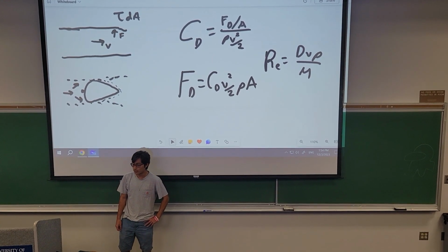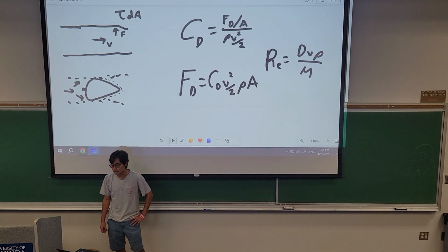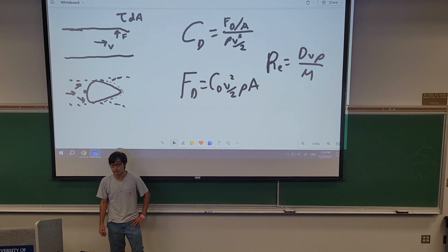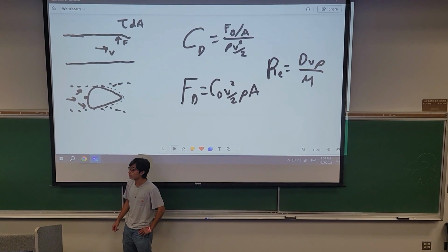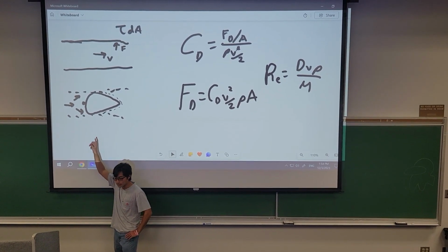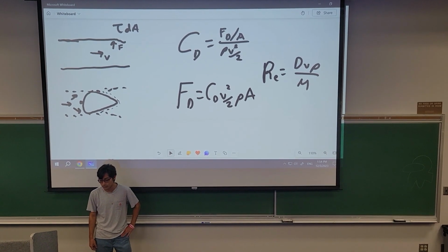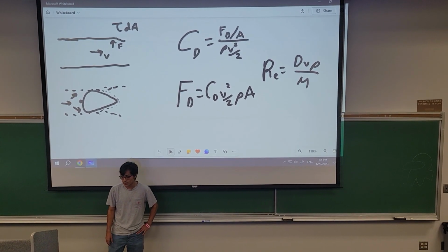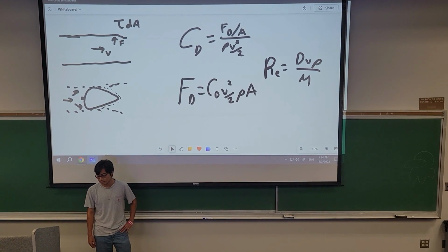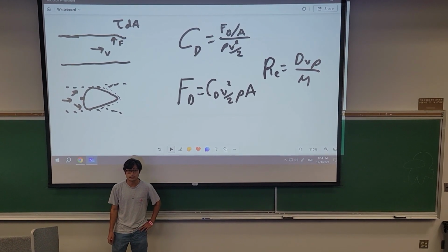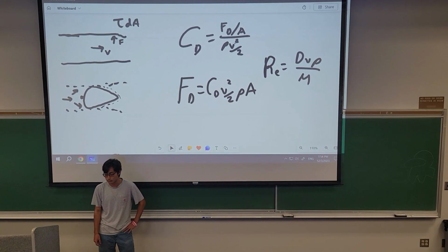Form drag occurs when there is a surface in the direction of the flow, causing the direction of the flow to change. At the center of the solid that is immersed in the fluid is the stagnation point. The stagnation point is where the velocity of the fluid is zero. The fluid then forms streamlines around the solid and accelerates, then decelerates. This additional force on the fluid movement is the effect of form drag.